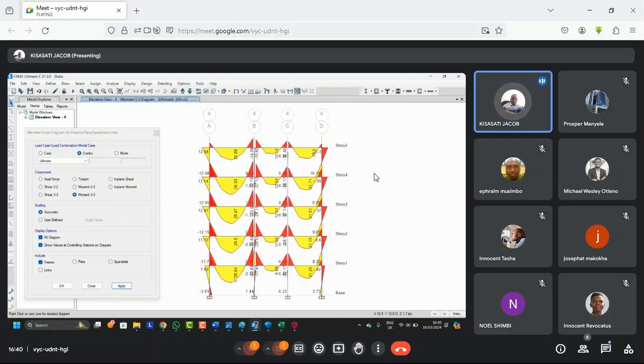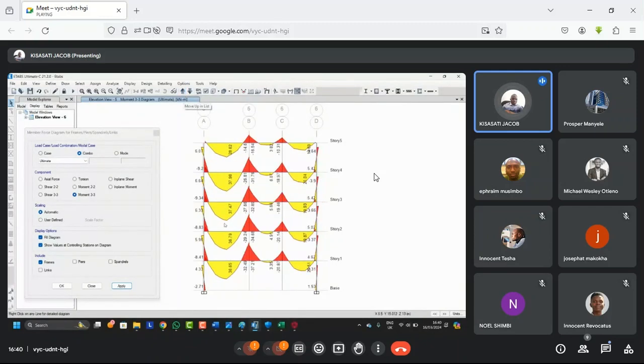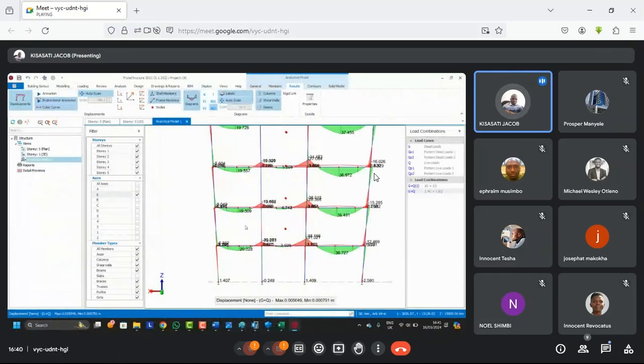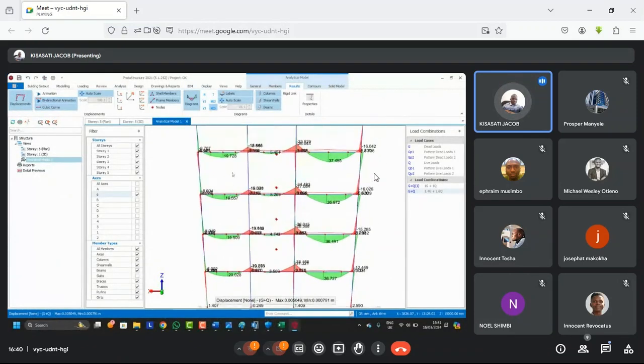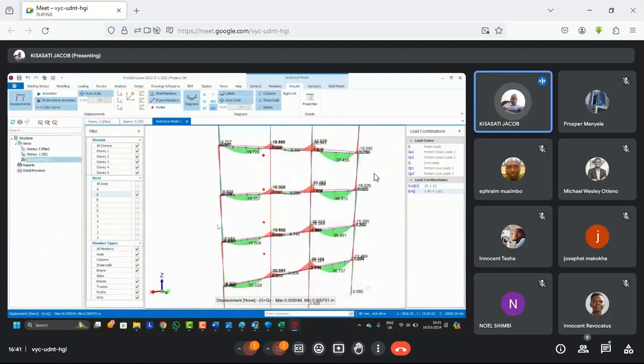Like the moments are at two. Let me check. As you can see, this one is also way below. It's even below 15. So these moments, when you go to Prota, are 20, 19, 19, like that, 5, 5, something like that. This one is 36 or 37. So for these moments, actually 3 to 12 will just work. So this is how you explore the analysis and confirm your results.